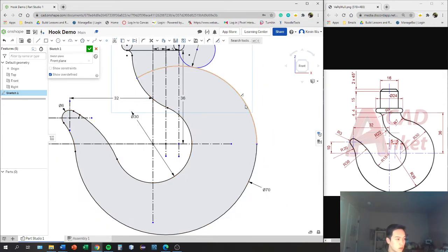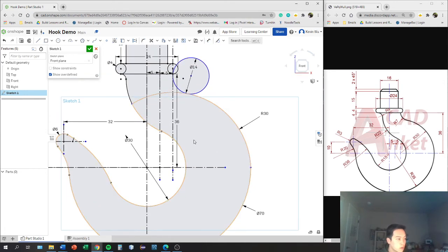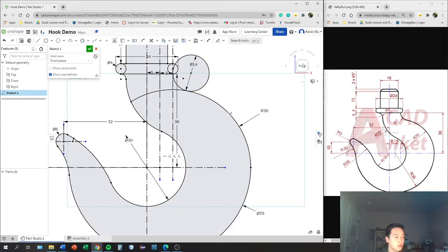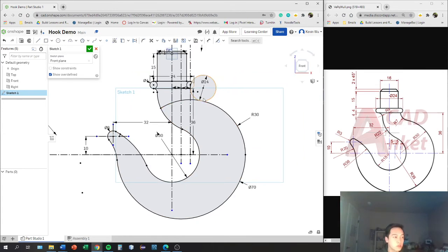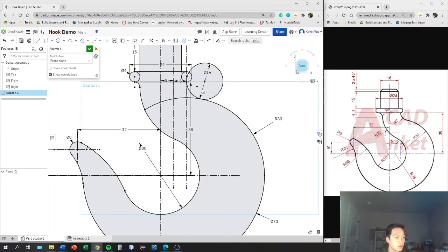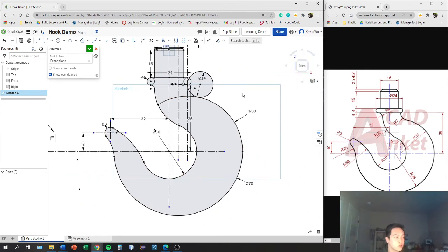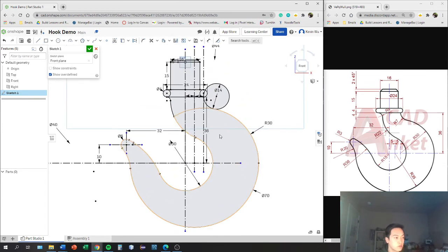And it looks like my thing is a little off, right? Oh, I didn't create a dimension. Alright, yeah, so if it makes that blue line, it means that your sketch is not properly constrained. So be sure to have the right constraint. Otherwise, your sketch can be disoriented and accidentally changed. And it's sometimes going to be a hassle to figure out.